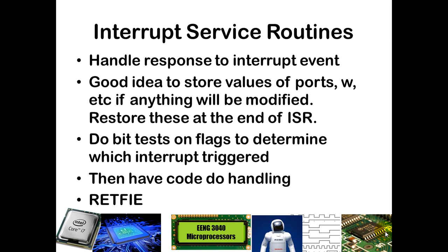The status register might be important in case you happen to be checking the carry bit or the Z bit somewhere in your logic, or if you need to even change banks within the interrupt service routine in order to address the interrupt. Then, if you have more than one interrupt, you should do bit tests to see which of the flags has been raised. That allows you to know which interrupt actually triggered this particular interrupt, so you know whether it was a timer or a port change or something else. And then you have the code there to do whatever you need to do to handle that particular interrupt event. So in the case of a fire, that would be go outside, wait, and then come back. And then you have the RETFIE at the end of the interrupt service routine.